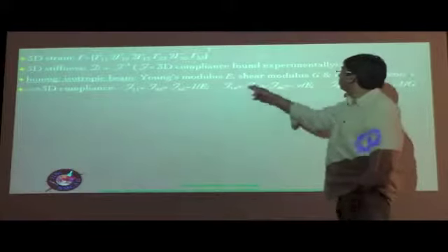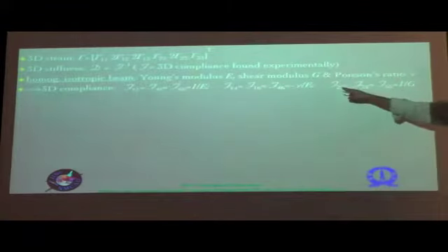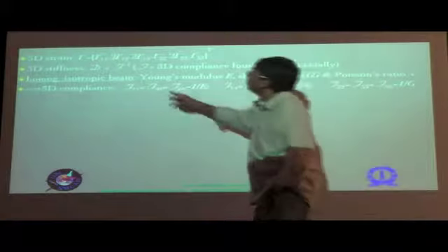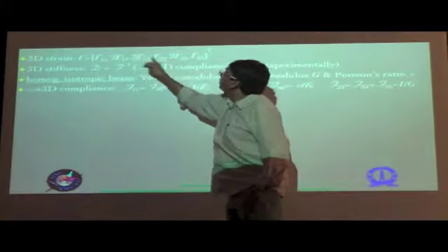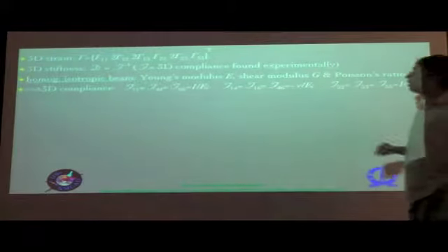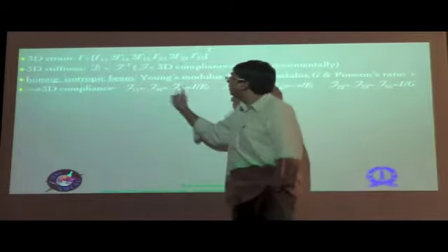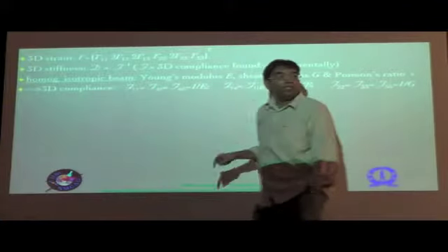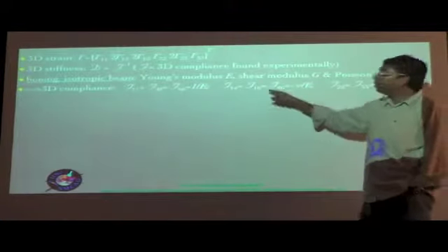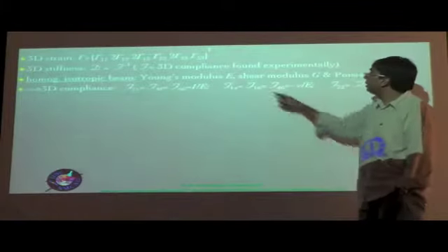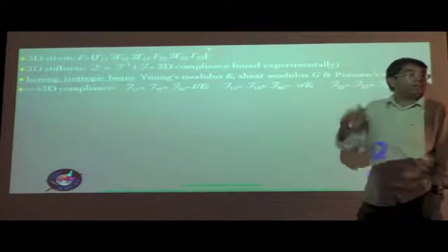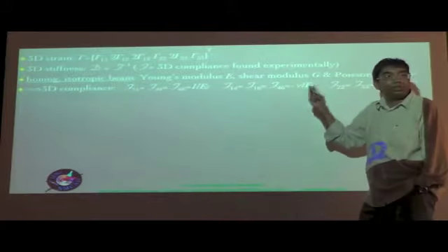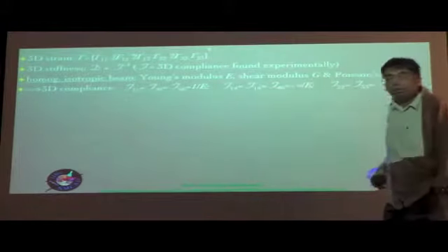And then the terms corresponding to the 2nd, 3rd and 5th are all shear strains, and corresponding to them you have the shear modulus obtained as its reciprocal. Then the coupling between these quantities, 1, 4, 4, 6 and 6, 1, are basically Poisson effects, coupling between the normal quantities. All of them are given by minus nu by E. In the special case where Poisson's ratio is 0, you don't have Poisson's effect or coupling between the normal strains and the normal stresses.